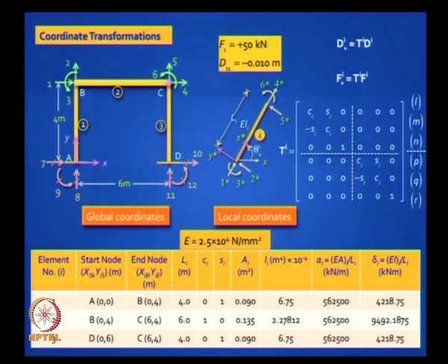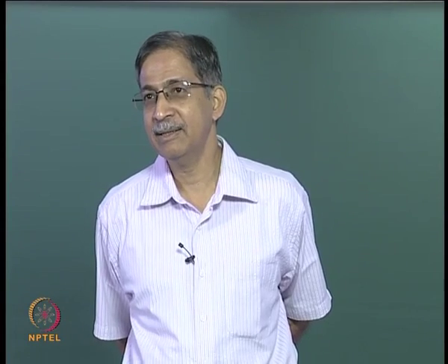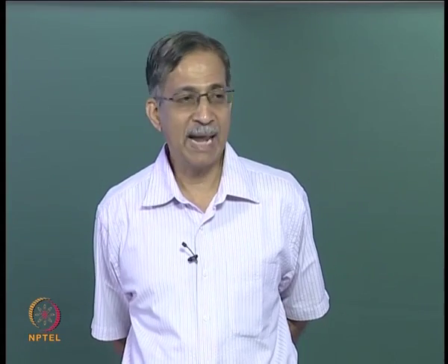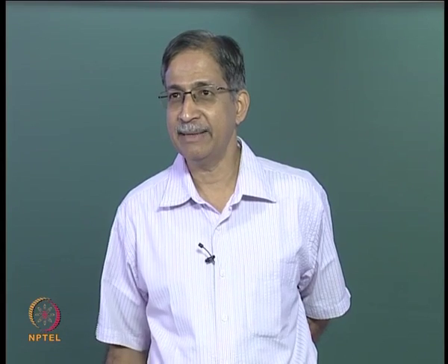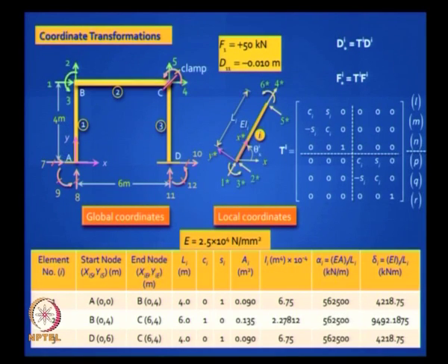So you see that hinge at C, and we are going to convert one of those degrees of freedom. Which degree of freedom? What is the number? 6. We convert it from active to restrained, and we introduce a clamp. So we do all that. Is it clear? We do that, and that degree of freedom goes to the restrained category. Nothing else changes.